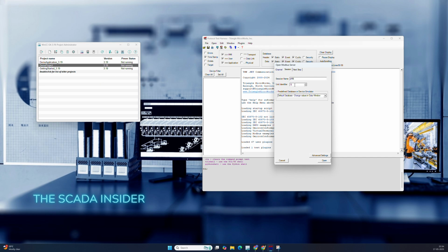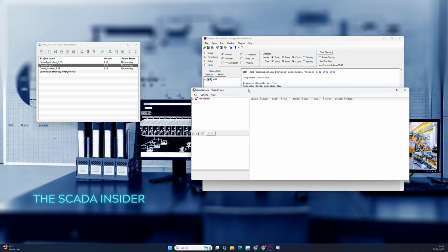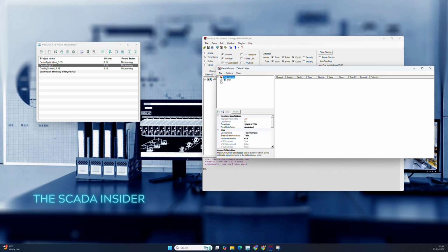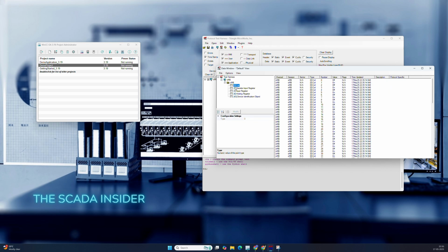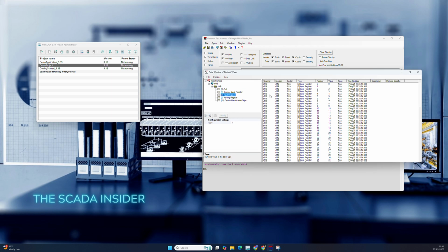Okay. Here we will set the unit identifier as 1, and in host IP I will mention 127.0.0.1, that is the local IP. In a real-time scenario, each device will have its own IP which needs to be configured in SCADA. Now we have configured the device and we get a data window here. As I earlier mentioned, we have different kinds of register types available. So here it is coil, then discrete input registers, holding registers. The changes which we make in the values will be reflected in the SCADA system.